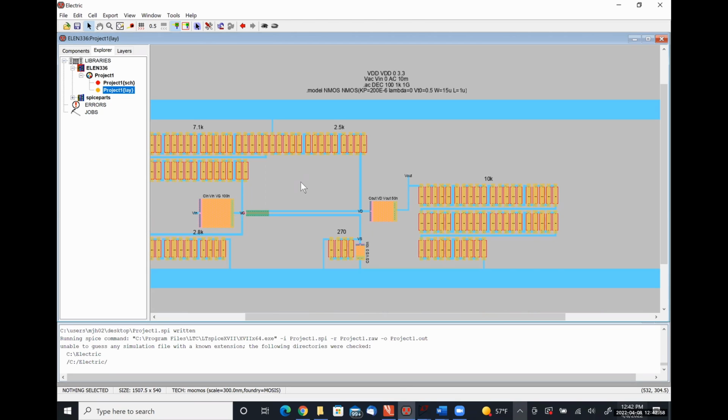So I'm saying I have an output capacitance between node VD and node V out that has a value of 50 nanofarads. That's the syntax here. So if I forget to export VD or V out, it just says that node's 0 and nothing works right. So you have to make sure that every node you reference in your capacitor statements is actually exported, or your circuit won't work correctly.